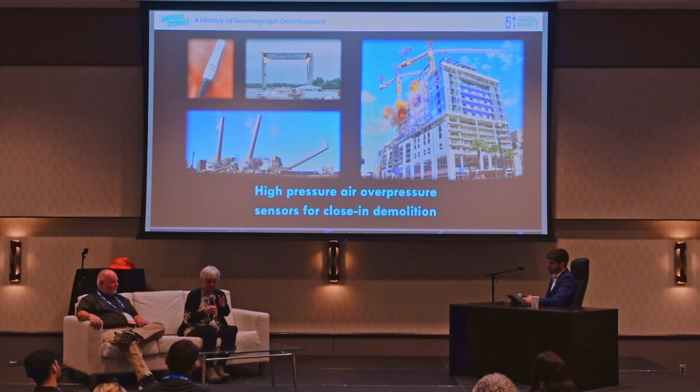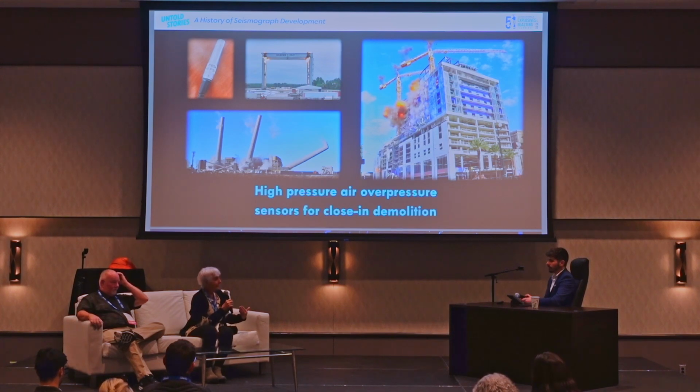It was about a 1/4 mile blast, and we'd pull them out afterwards and wash them off and look at the pulverization of the glass beads. And sure enough, right at the initiation point, the beads were fine. But as we went down that 1/4 mile, by the time we got to the very end, there was not a single bead left because they were shooting way too fast. So we combined the pressure sensor, we correlated the pressure to the percentage of beads that were crushed to show the mine that they had the wrong timing and they were wasting a whole bunch of energy. So that worked out really well.